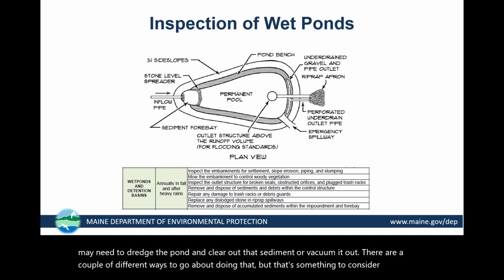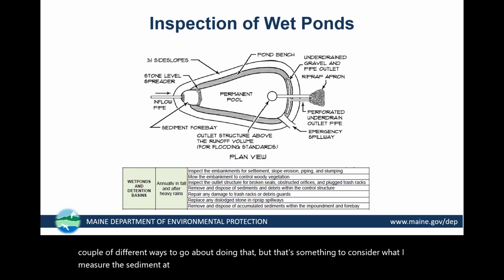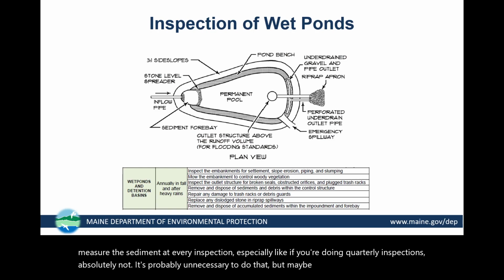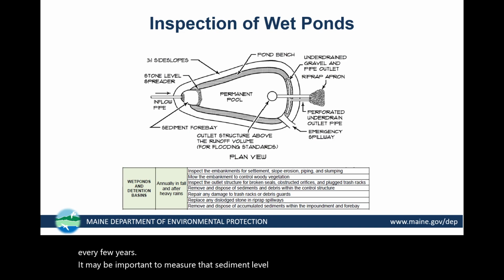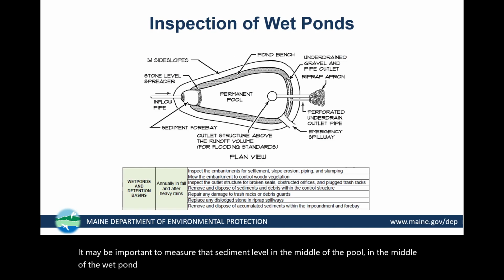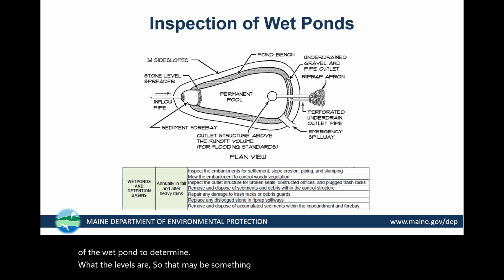Would I measure the sediment at every inspection, especially if you're doing quarterly inspections? Absolutely not. It's probably unnecessary to do that, but maybe once annually or every few years, it may be important to measure that sediment level in the middle of the pool, in the middle of the wet pond, to determine what the levels are. So that may be something to consider as well.